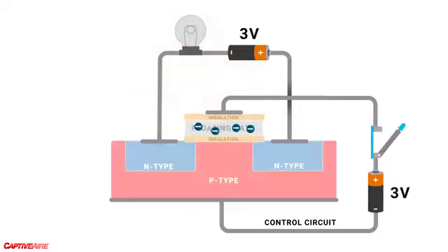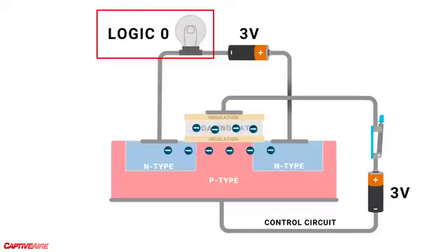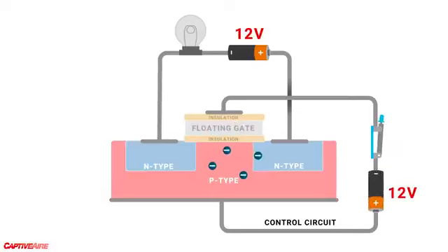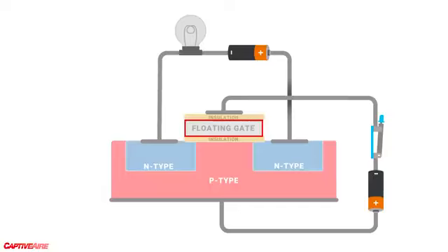Now when we try to flow electricity across the transistor at a normal voltage, the electrons stuck in the floating gate reduce or even prevent the flow across the transistor. We can again read this flow and determine it's now too low, resulting in a logic 0. If we wanted to reset the transistor, we could apply specifically high voltages across both circuits, attracting and releasing these electrons back into the body. So in essence, by controlling the presence of electrons in this layer, we can allow the transistor to flow or block this flow permanently or until we decide to change this.